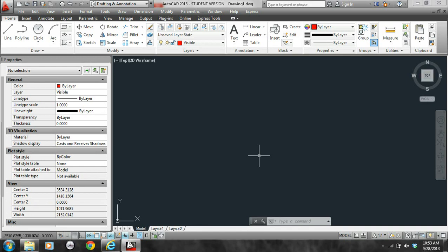One has a diameter with a limit of 28.52 to 28.57, and that's the whole part, and the raised portion has a diameter of 44. And there's also another one on the drawing. The other two objects, one is kind of in the shape of a pill. This is called a pad. It's on the left side of the drawing, and again, this is a raised piece of metal.